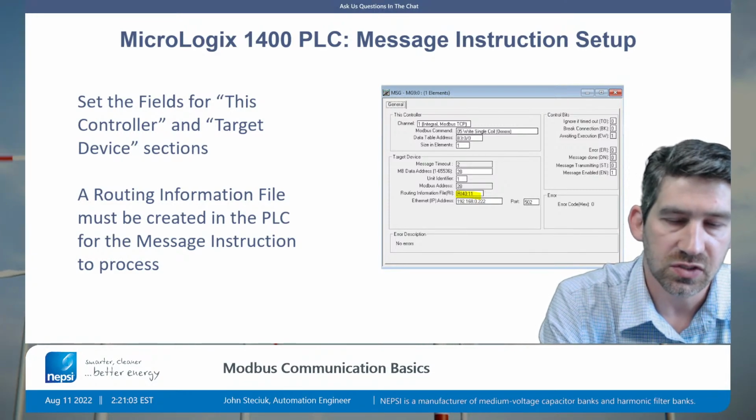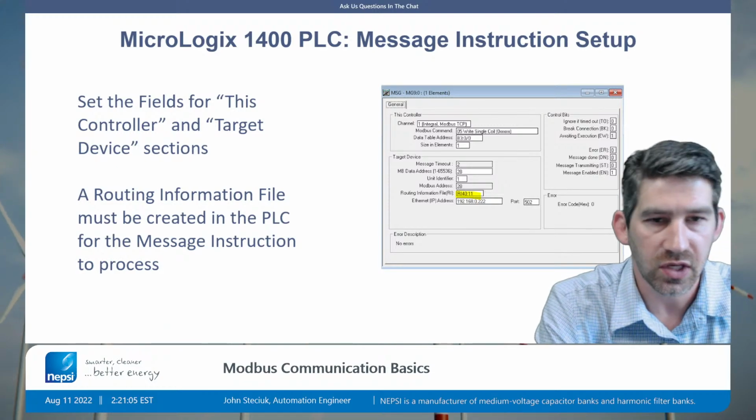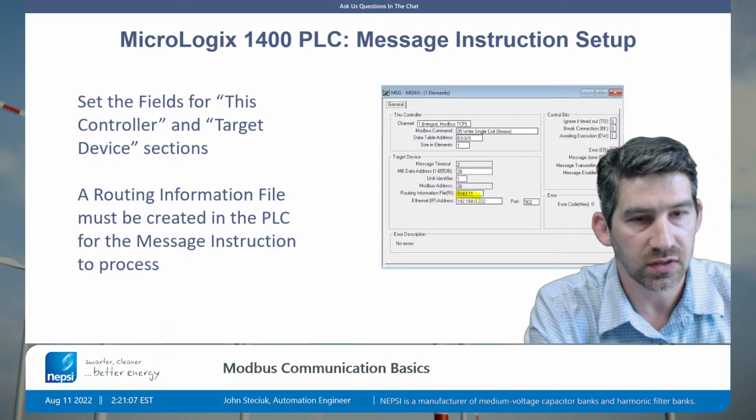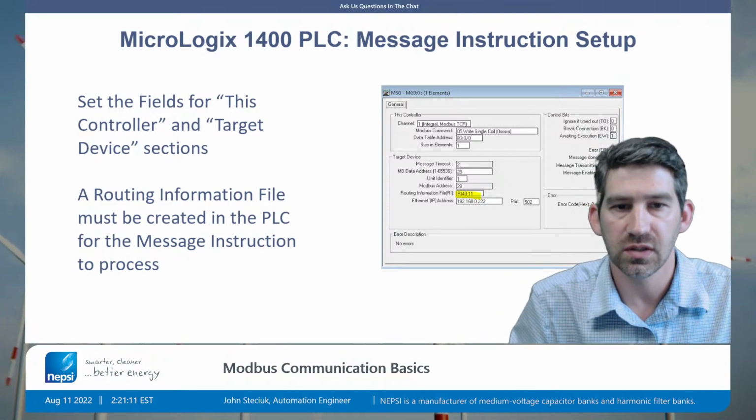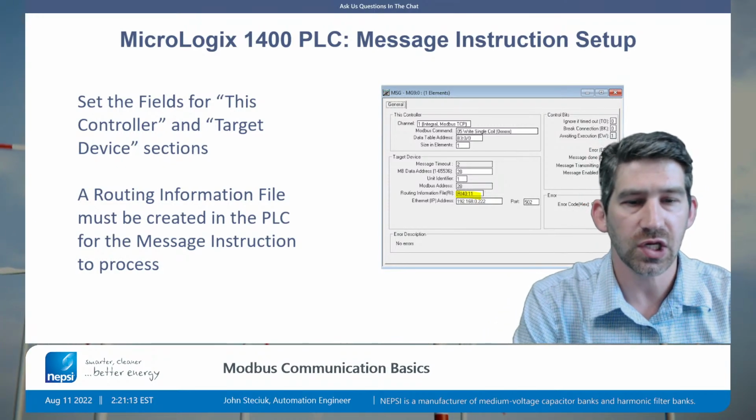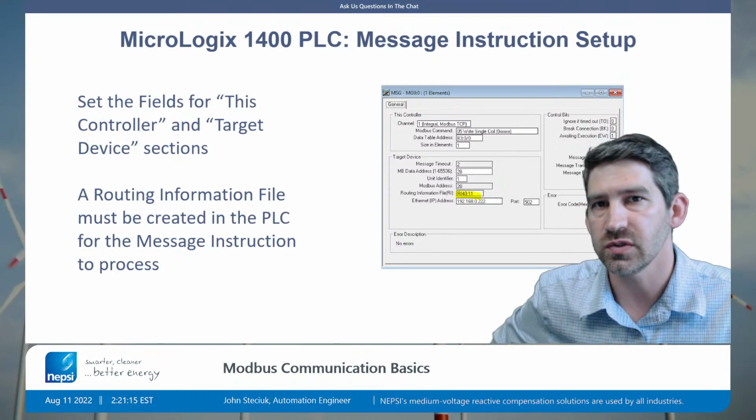And this message instruction is also a good location to do some troubleshooting. If you're online with the Micrologix 1400, then you can check here for error codes if you're having trouble with your communications.